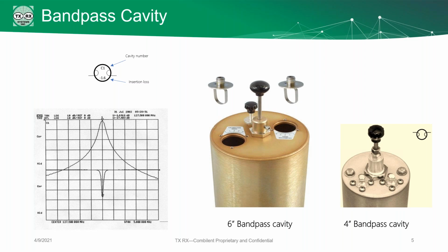The metal shell serves as an electrical ground, while the shape and size of the orientation of the thin metal loop under the connector plate determines the filter curve, as you can see in the graph on the left. By changing the connector loop to a different type, we can produce different filter curves. This design greatly improves the flexibility of our product family and is one of the key advantages of the TXRX filters.